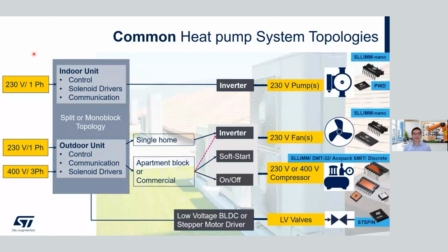That means the heat is extracted from the outside environmental air and is converted into heat in the water part, the liquid part inside the house. Sorry for that misspelling. Normally these air-to-water heat pumps can be either built in a split topology or a monoblock topology.